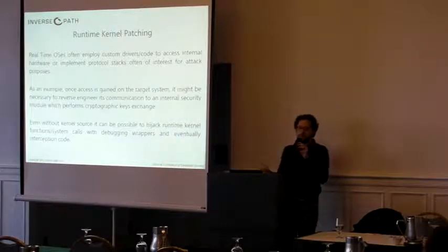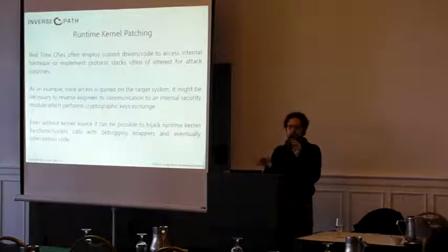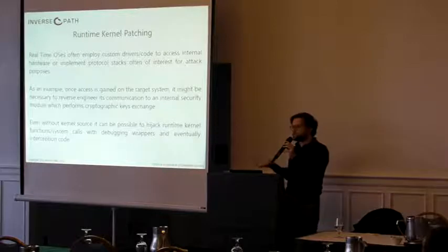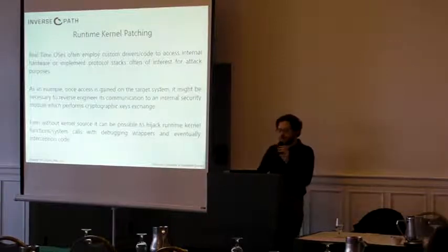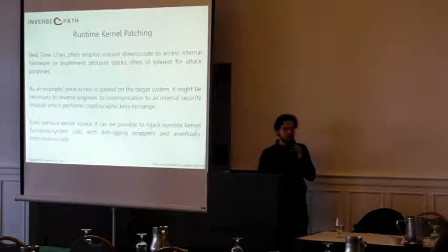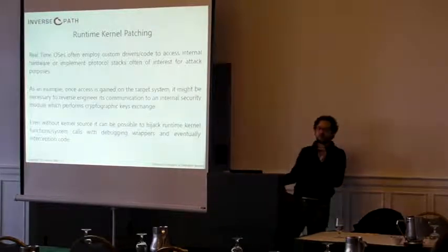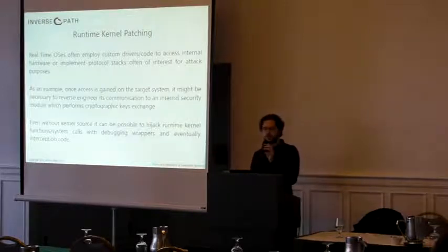One of the prime examples is a cryptographic key, which the operating system is actually using at some point, and that is stored somewhere on hardware which is either tamper-proof or really hard to identify and access. Most embedded systems, even if they have a full-blown real-time OS that has the concept of kernel space and user space, have a habit of doing everything in kernel space, with drivers in kernel space that pretty much do everything.